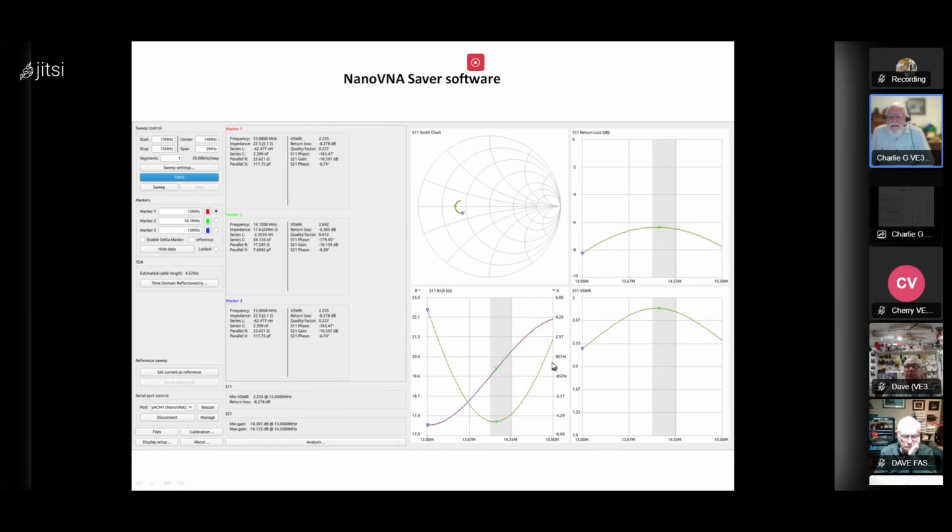I'm showing plus 857 milliohms, minus 857 milliohms, so I'm right in the middle. I'm just about perfect as far as reactance is concerned, but my resistance is very, very low. It's way down in the 17.7 range. If I look at what the marker is telling me, what this tells me is, hey, you cut the wire the right length, but the impedance is wrong. You need to fix it somehow.